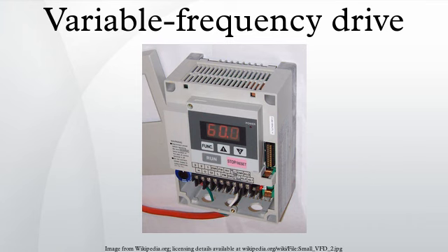In rolling mill drives often 200 to 300% of the base speed is used. The mechanical strength of the rotor limits the maximum speed of the motor.